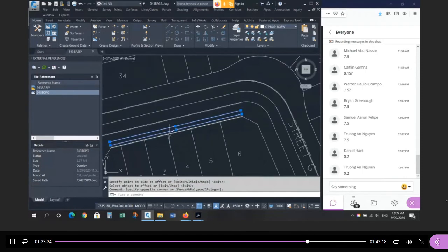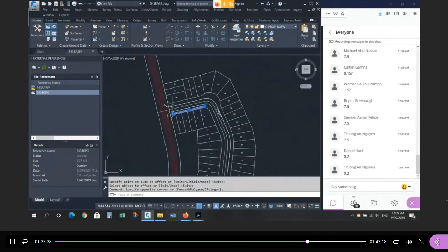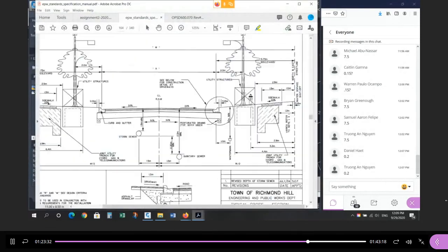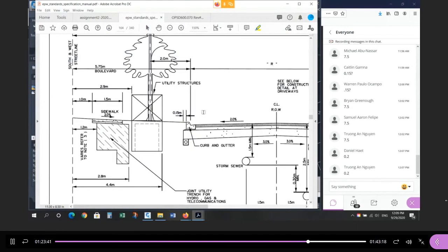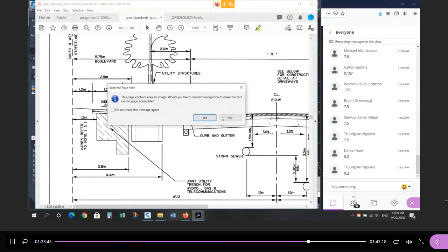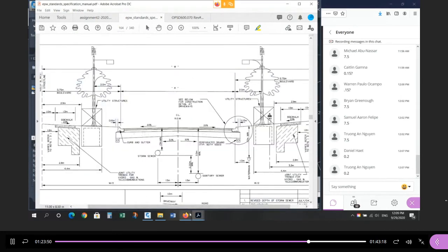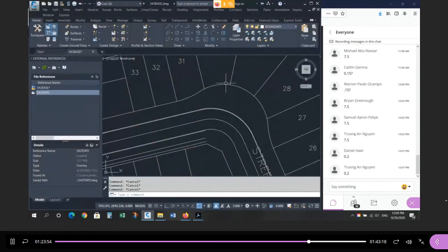So that's your sidewalk. And that goes all the way through the subdivision around the bulb and back again to the other side. So you're going to have sidewalk on both sides. How do I know? Well, there's a sidewalk on this side, and there's a sidewalk on this side. So you have to draw the double line sidewalk throughout the subdivision. Okay, so that's the sidewalk. A little bit of interpretation, you have to, so this is your typical 20 meter right of way, remember? 20 meters wide, that's where you put the sidewalk. How are you going to deal with the elbow or the crescent?